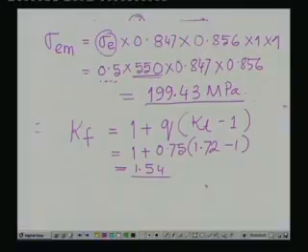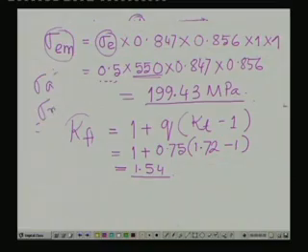Now, it is a simple situation that we can put all the values in the Soderberg equation. This Ka, this sigma A endurance for this one, then we require the sigma A, which we have already computed, and we have to put the value of sigma M. What more do you require?